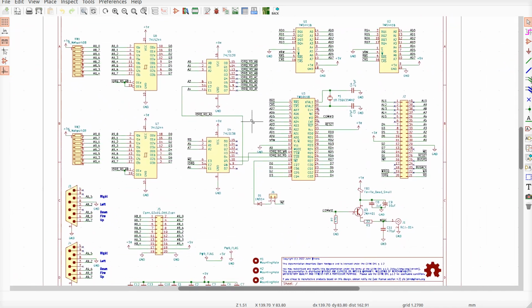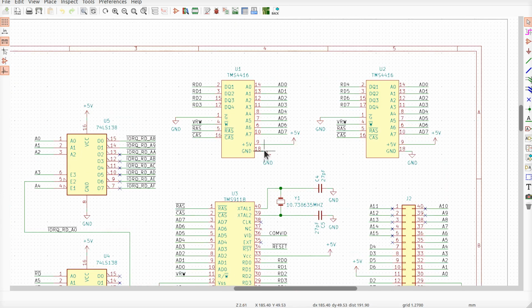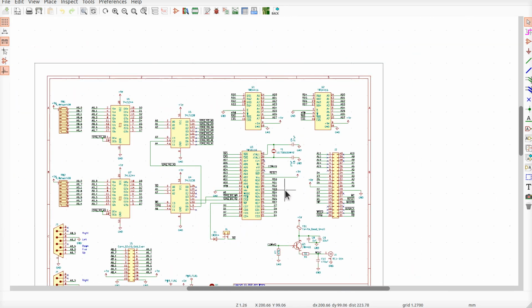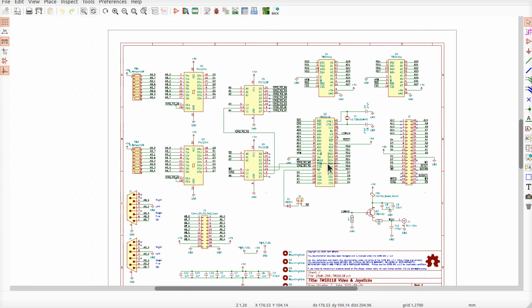Now, if you've not already built a VDP and you're excited about doing so, why don't you wait until I release this along with the new Gerbers. It'll be revision 2. Revision 0, as you recall, had the power hooked up backwards on the DRAMs, which drove me absolutely nuts. That's this up here, okay? Revision 1 is what we have here. I'll move on to Rev 2 with another jumper in order to make that work. All right? So we're moving along in a forward direction here.